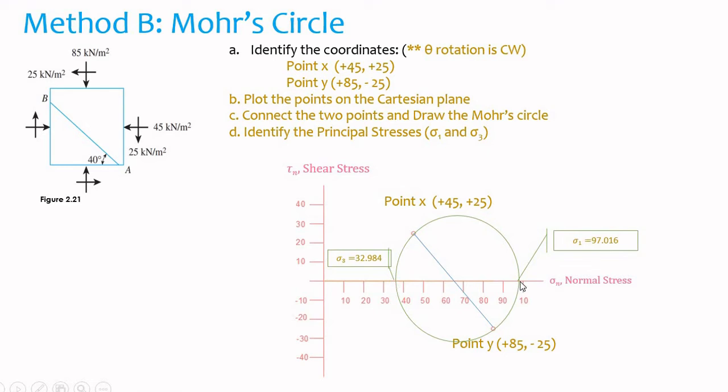I actually plotted this using AutoCAD, that's why I came up with 3 decimal points. But if we are plotting manually, we allow up to 1 decimal point. If we are using the compass to plot it, we can read up to the first decimal. Since I plotted this in AutoCAD, I just got 3 decimal points as well.